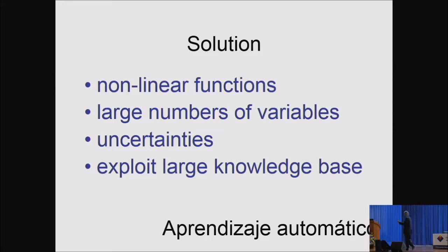Now, people in welding don't like martensite, because martensite is associated with bad toughness. But if you remove carbon, then martensite is actually very tough. For example, rocket motor casings are made from martensite with zero carbon concentration, Maraging steels. So martensite is not bad if you remove the carbon. Keep the carbon to a minimum.